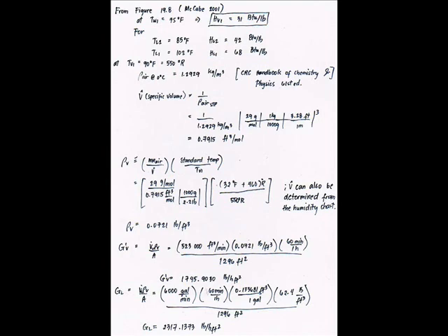The density of the vapor, ρV, can be calculated by the equation ρV is equal to molar mass of air over specific volume of air at standard temperature and pressure, multiplied by the standard temperature over the inlet air temperature. Since other variables are already given or computed aside from the specific volume, we solve for it. Specific volume can be determined from reciprocating density constants or from humidity chart as from figure 19.2 from McCabe 6th edition. Variables will be converted if necessary to get pounds per cubic feet density value.